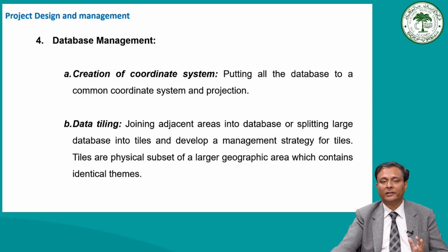So putting all the database to a common coordinate system and projection, the coordinate reference system, CRS, which you might be learning in your lab exercise, is one of the most important functions of spatial information science. It is a coordinate-based local, regional, or global system used to locate geographical features that occupy a position in space.